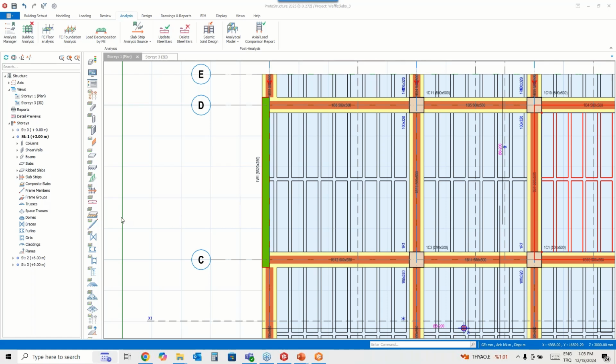Mr. Abu Jabal, yes, it's possible. You can also add hidden beams as well, and you can create such a zone with the converting members to the real beam elements and place the slab members around this region.